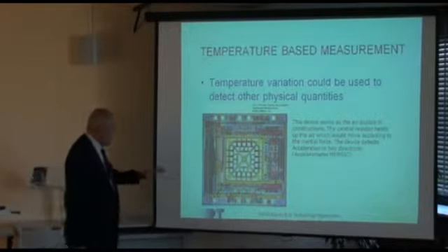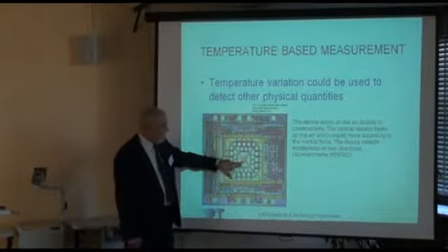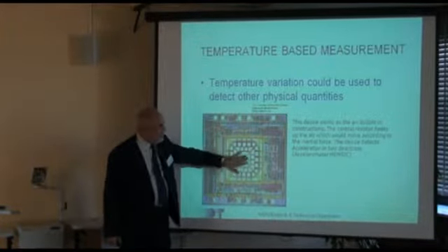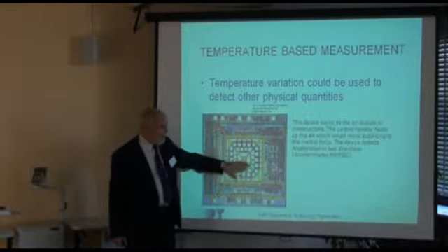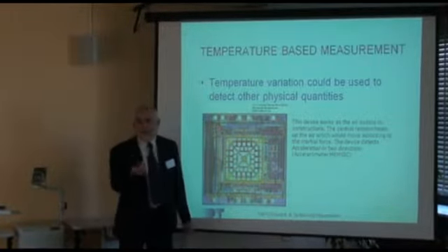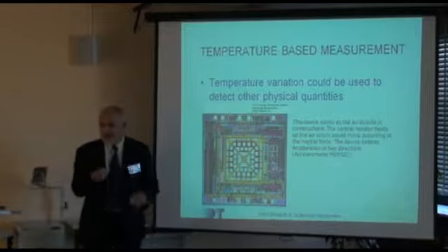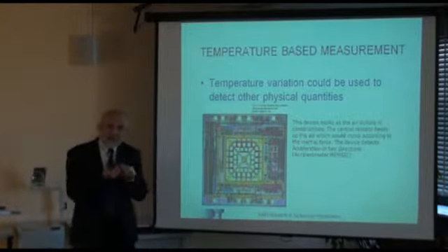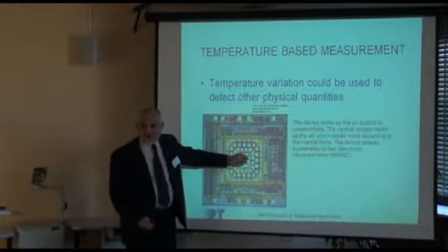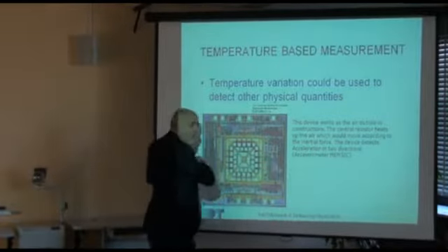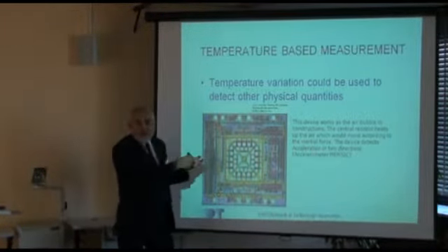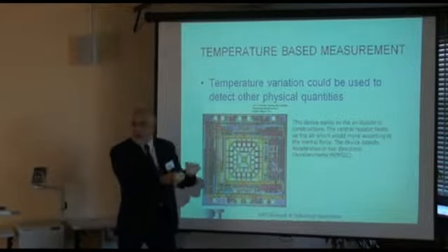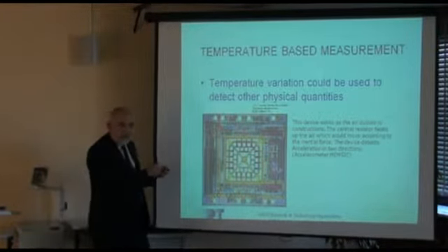And what is the principle in here? The principle is the following. I have a heater, and I have an array of temperature sensors. Now, this heater is continuously heating slightly. It's not a big temperature, but it's heating a bubble of air. Now, when I move this left or right, the bubble will remain inertial, in the position. The trend is to remain in the previous position.